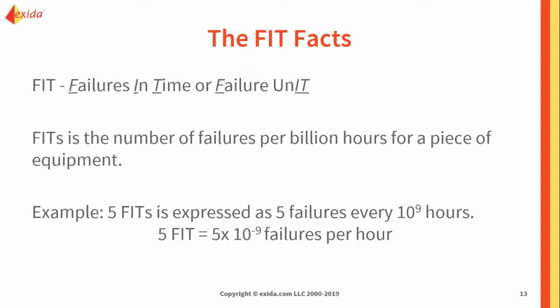These failure rates and FITs are very important pieces of information to provide to your end users if you are an OEM. If you're an end user, this is very important information to ask your OEMs for. These failure rates can be entered into significant portions of your design, like your SIL verification tasks and your PFD average, or your probability of failure on demand average.